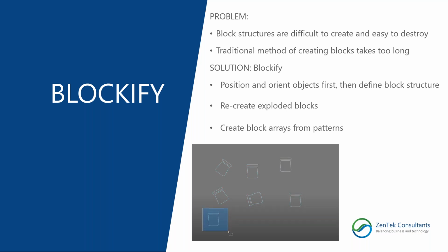So that takes several steps, and then usually after that you have to go and place the block in your drawing, because for most of you, you're creating blocks because you're going to have multiple instances of a set of objects. So you'd have to manually go in and place all of those blocks. That takes at least a couple of steps.